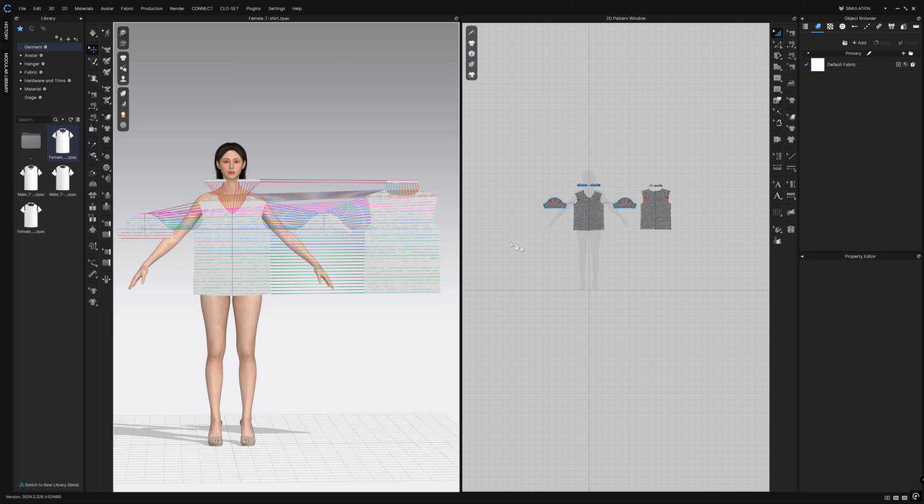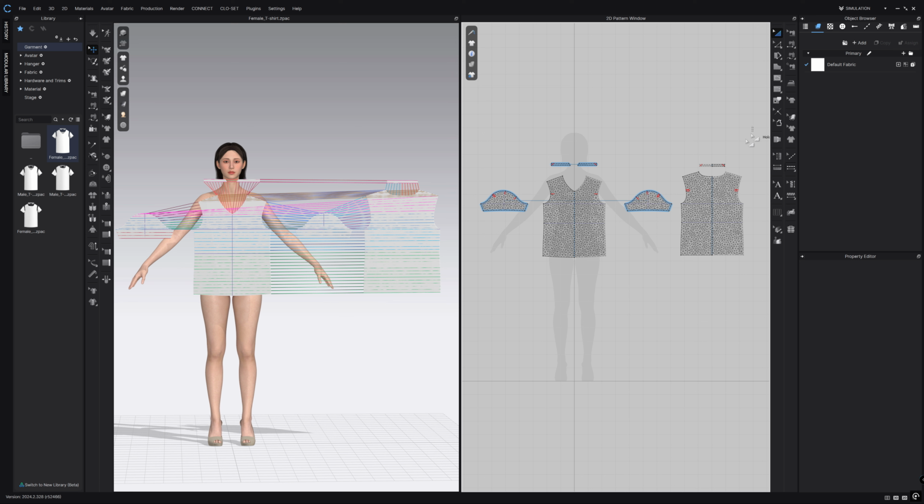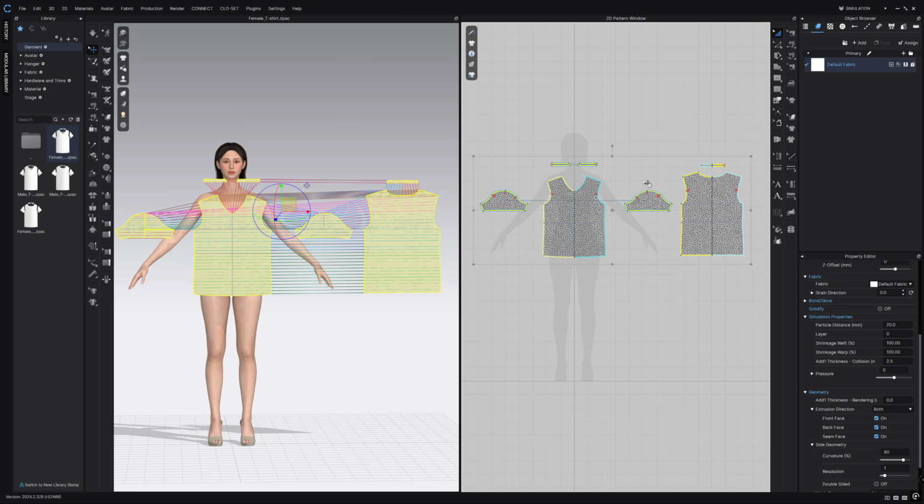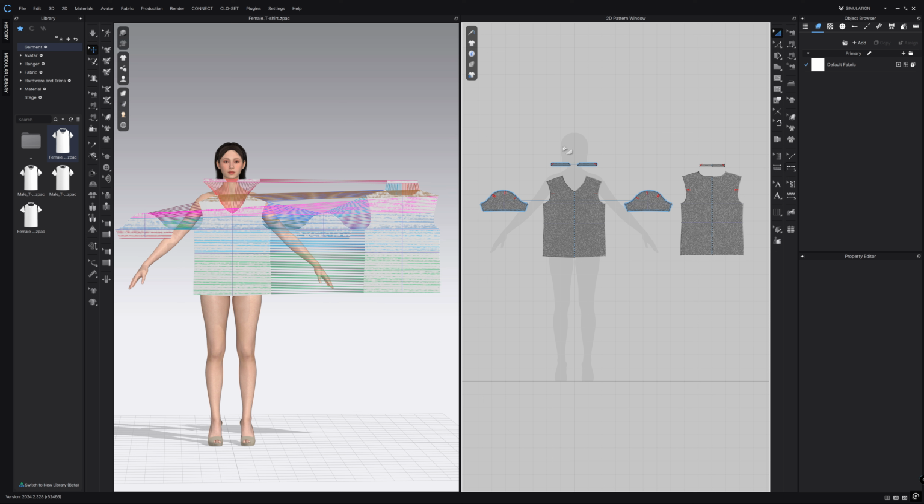All right, what's next? Render meshes. Usually the point of them is to have a higher thick mesh for beautiful visualization. So what we want to do, the higher res, is change the tessellation of these panels. The default tessellation here is particle of 20, which is 20 millimeters, so about 2 centimeter edge length. If you change this to 10, you will see we end up with about 4 times the resolution. So this is quite nice, and I think we should stick with it for now.